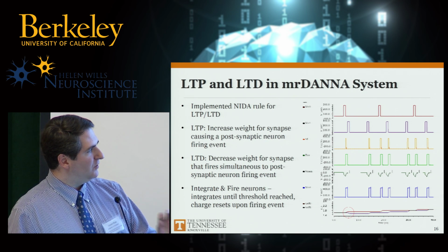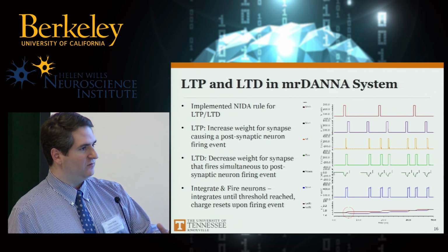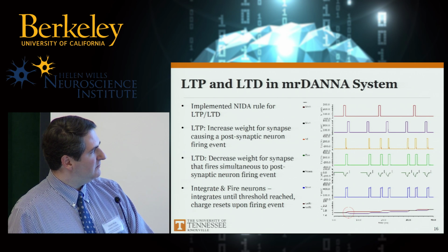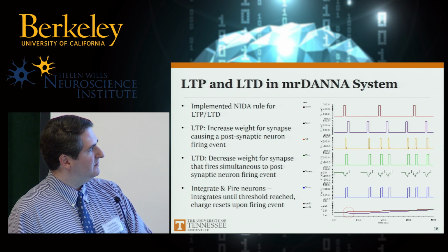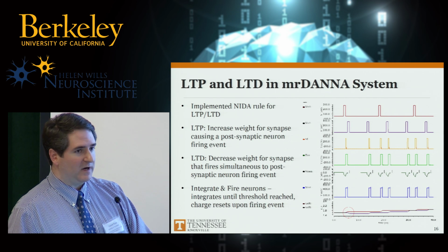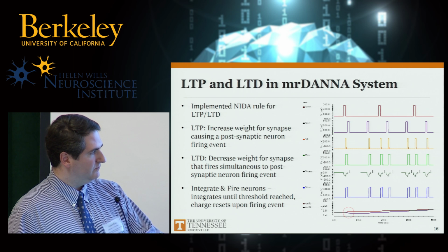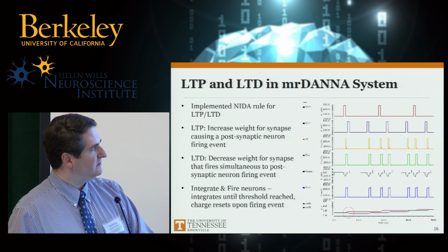And the neuron has a very low threshold. As soon as it gets one spike, it's going to fire. And you can see that down here with V out, where it fires. So V in, this first input fires first. That's enough to cause the output to fire. And since that caused the output firing event, we'll see that this is the input. The red weight down here is its corresponding weight. It increases its conductance, meaning it increases its weight, so it potentiates.